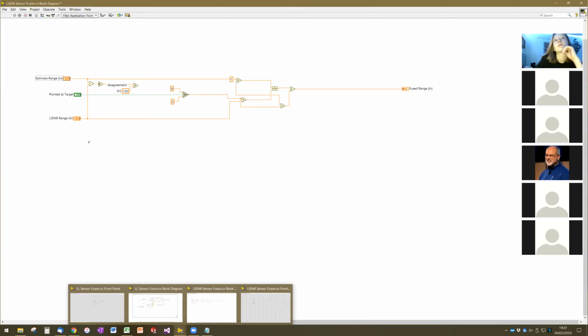Now, if we're very careful about how we mount it, we may be able to immediately know when we can't see with the LIDAR because the Limelight will go out. And that would change our decision-making process, right? There's not a fixed right answer to this question. We have to evaluate with real data and with how the robot actually performs which sensor we should trust more. And in certain situations, this may be different.